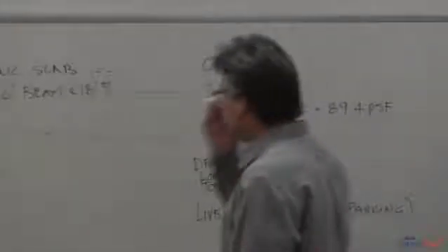Here? Yes. Is that 18 feet on center? This is the beam spacing at 18 feet on center. The O/C is just something you have to get used to. It doesn't matter what material you're talking about. That's a standard engineering thing to describe spacing. Okay, so all I'm doing here, this confuses everybody every year, but